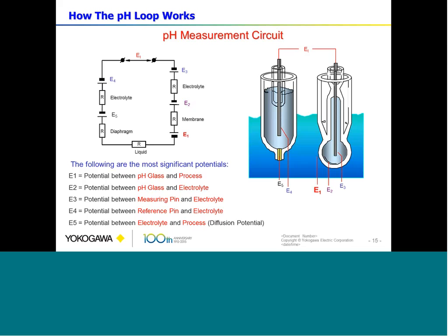And then there's the ides of March. Well, that's not true. There's a bunch of ides: sulfides, cyanides, bromides, all of which will connect and coat with the reference electrode because it reacts with the silver to form a silver sulfide, which again is going to cause errors in the measurement and give us an inaccurate reading.